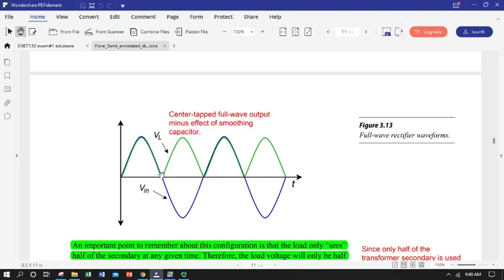every time. And another thing we can notice is we just increased our frequency, because we now have a waveform that is defined by just this sort of positive set of camel humps, if you want to call it so. So one waveform is no longer the sinusoidal up and down, it's just the half. So we've now completed a single waveform of the green curve here at this point. So at the time elapsed for a single sinusoidal waveform of our transformer secondary, we've now had two waveforms of the signal going across our load.